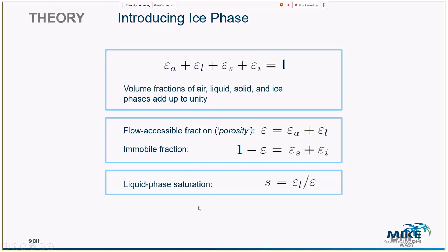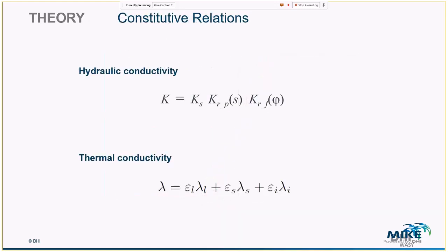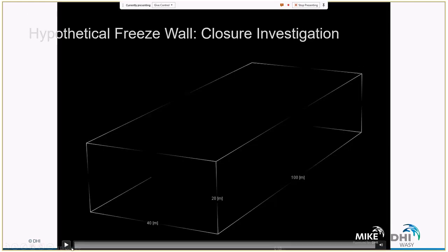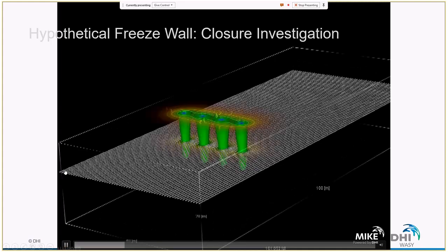So what is the part of the fluid volume which can be subjected to freezing? And with the user-defined freezing function, we can decide the degree of freezing for multiple materials. You can control the conductivity, you know Richards equations to reduce conductivity due to saturation. Now you can have a conductivity reduction due to freezing. Etc. So here I have a nice video which simulates the injection of a refrigerant into the system.